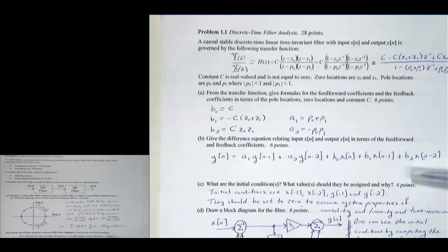The one I propose here is we want to put zeros in the stop bands. We don't want to put zeros in the pass bands, because it's not a pass band anymore. So this first filter is just a bandpass filter. So I can put 1 zero here and my other zeros here.